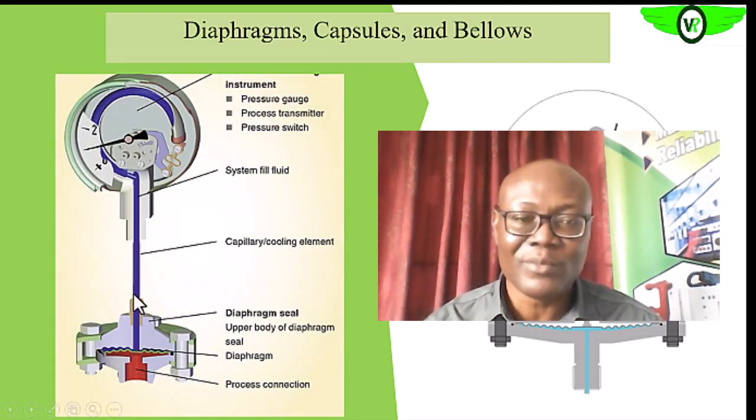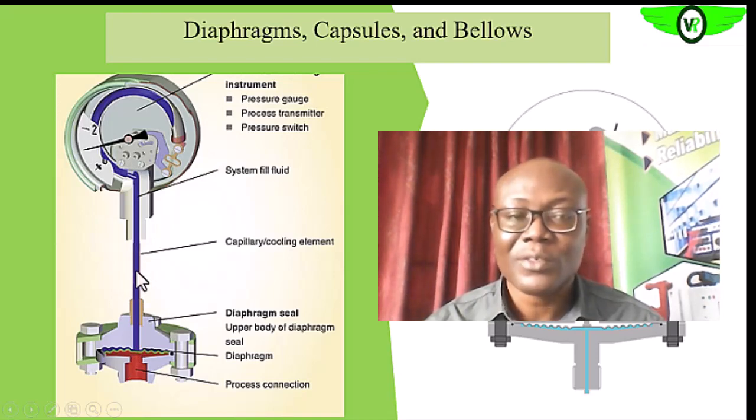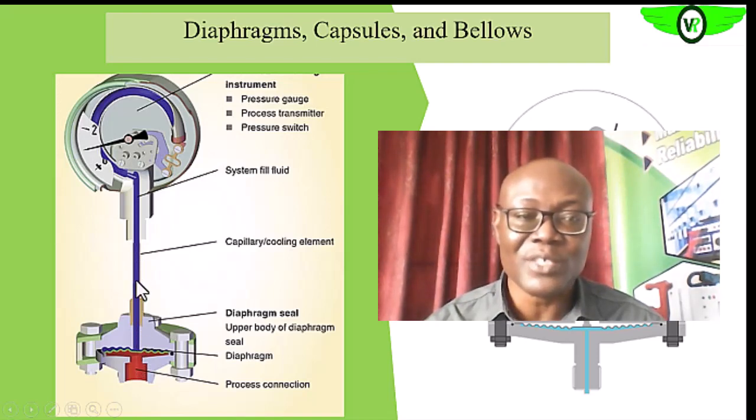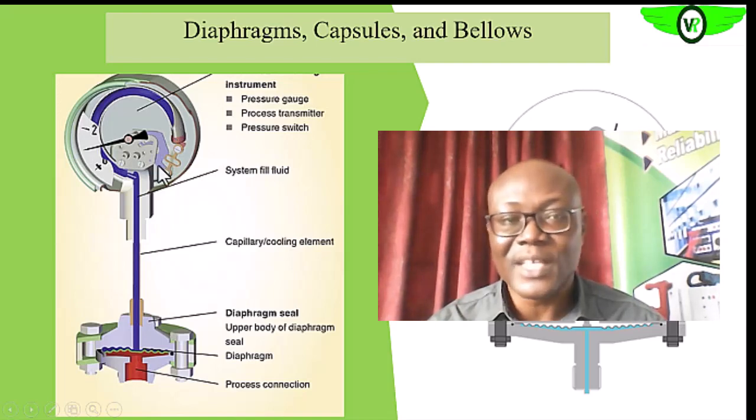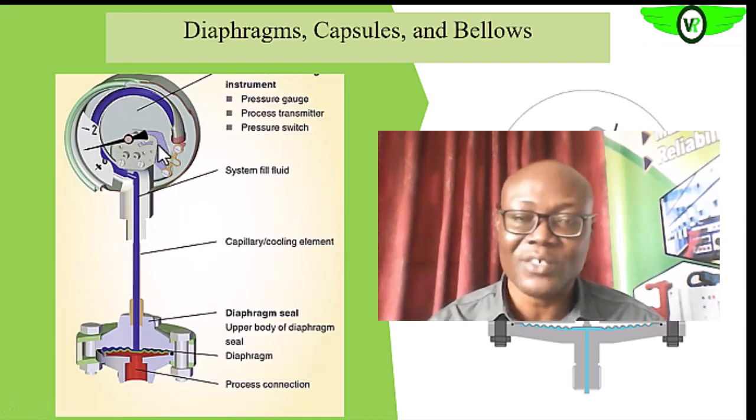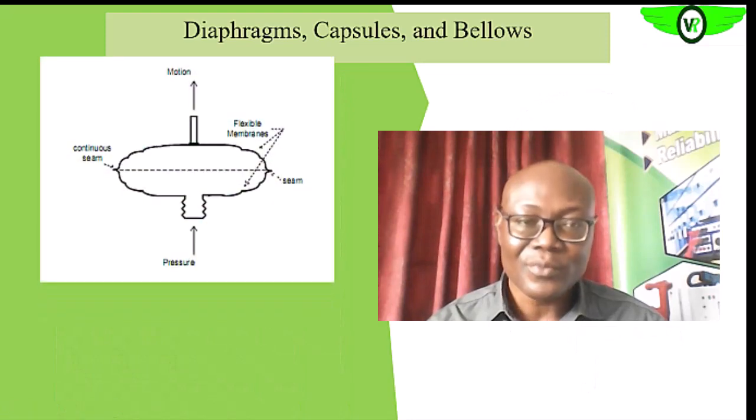this diaphragm, this capillary, okay, that drives it. Could be fluid also. Are we getting it? Fluid could be contained here. So as this one is stretching, it increases the pressure here, and that fluid can transmit the pressure to this part of it. Could also be a Bourdon tube that can cause the stretching here, okay. So here we have two of such diaphragms.